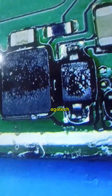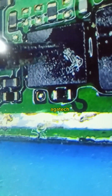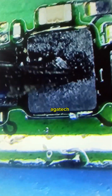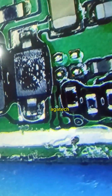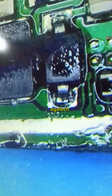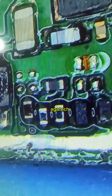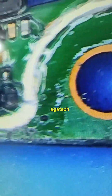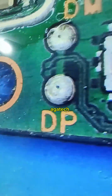From the microscope, you can see this is the backlight circuit. This is the IC that controls the backlight. This is the inductor, and this is the diode. And from here, the signal goes to the screen connector. So you can see the signal go this way to the screen connector.